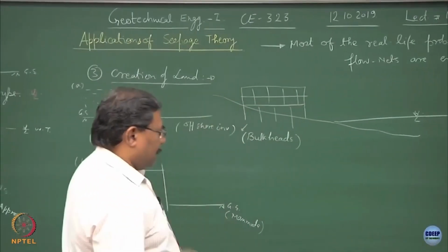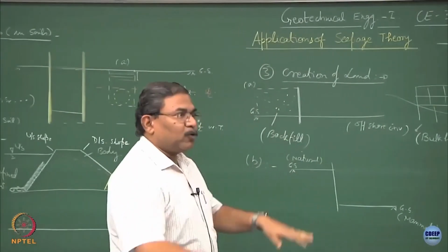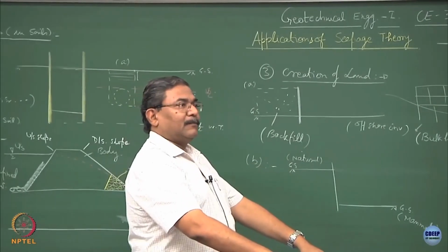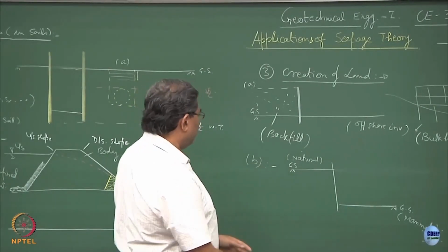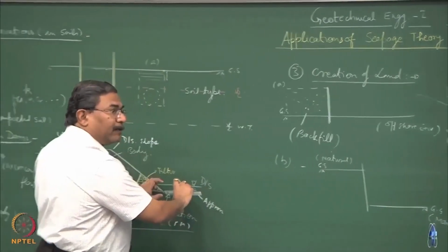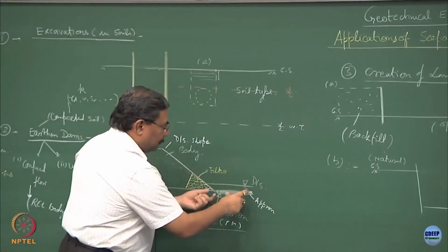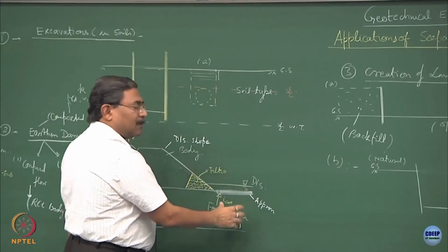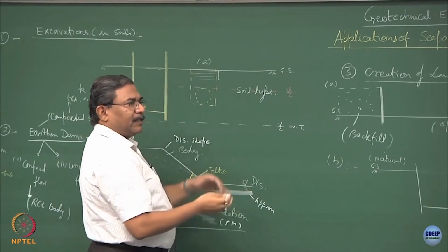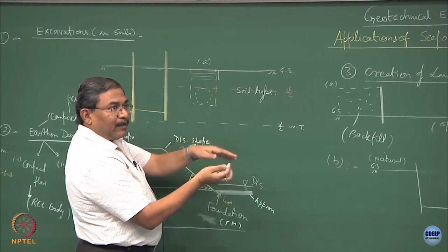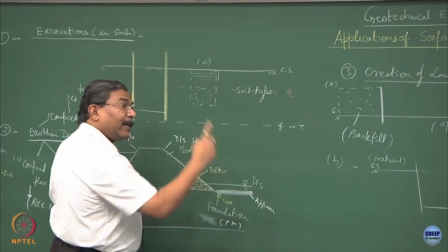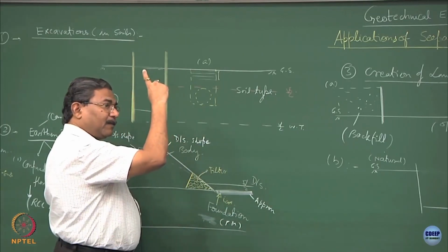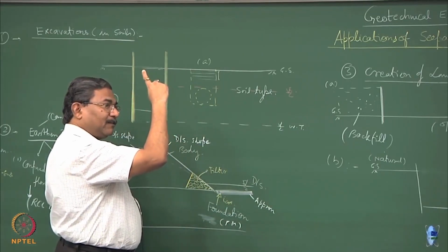So, see the normal practice is, suppose if I want to suppress something, clear, what I should be doing? I will create a thick pad of concrete so that this mass gets added up to the soil mass. So, apron by definition is a thick mass of concrete which is going to negotiate with the F force. F, you remember, the seepage force.